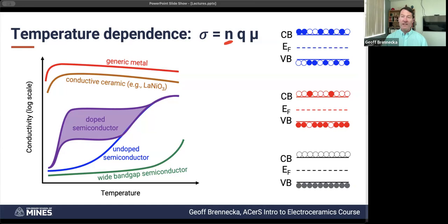And so if I want to increase the conductivity by 10 to the 18th electrons over what I had before, then I put in 10 to the 18th dopants in the volume that I care about. So it's essentially 1-to-1 for absolute perfect doping within a semiconductor.